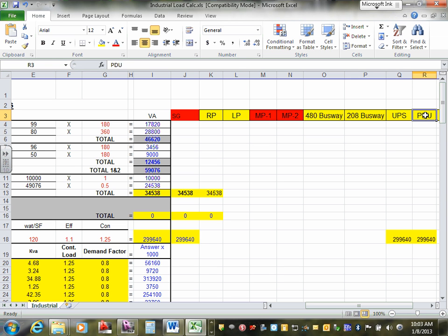For us, if you look at the project, we only have one UPS, because the building is small, and we're feeding 2 panels from it. But the 2 panels are going to be carrying the same load. So for redundancy, if the panel was a 300 amp, it's going to be 300. So that's why we size only one of them. Cool? So all of it goes to the one, it's just there's 2 of them that are the same. Yes, for redundancy. Good point. That's my PDU and UPS.